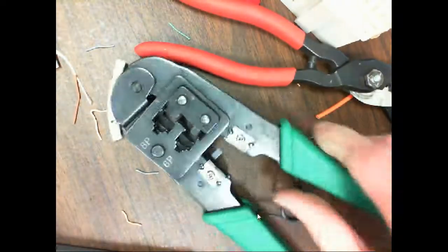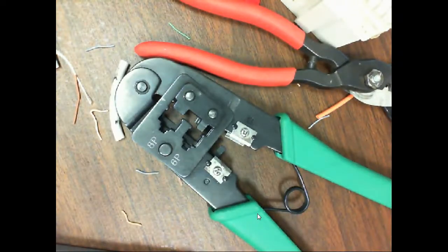So look, I want y'all to look at the end and make sure you understand what I'm talking about, where you can see the little copper dots on the end. If you can't see that dot, it means that one of those wires is not all the way up to the end, and when you crimp it, it's not going to crimp good, right? Because it's actually taking the blades on that connector and pushing into that insulation, cutting into it and making your electrical connection.